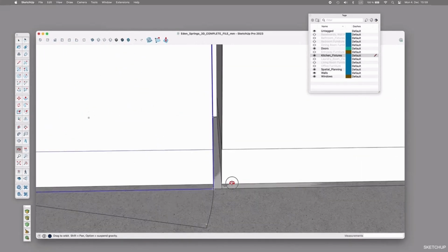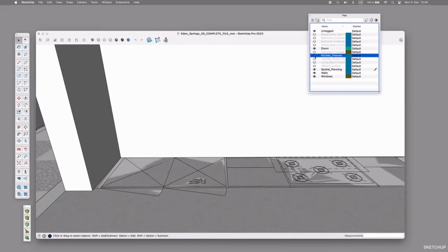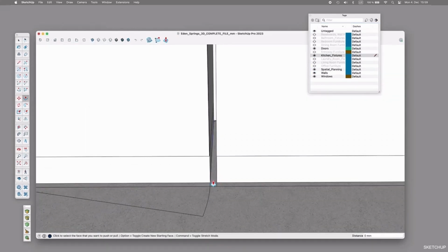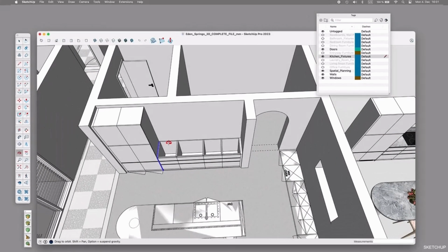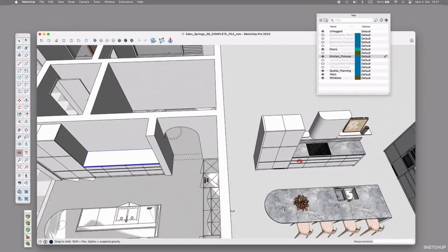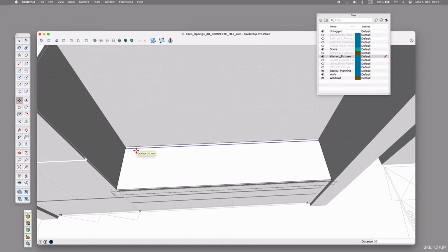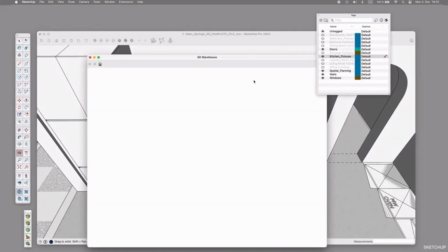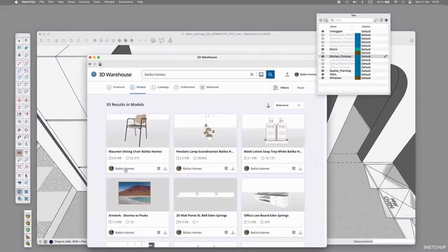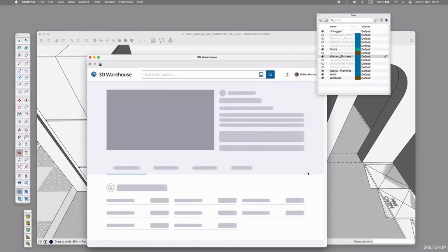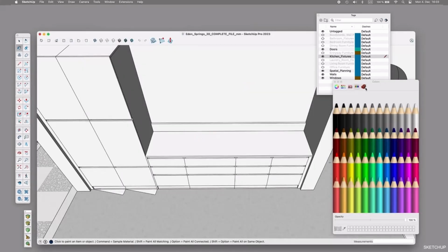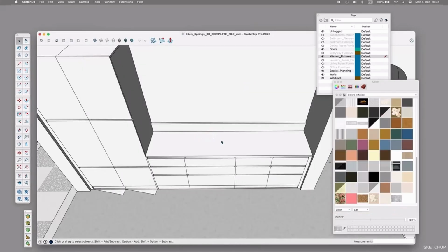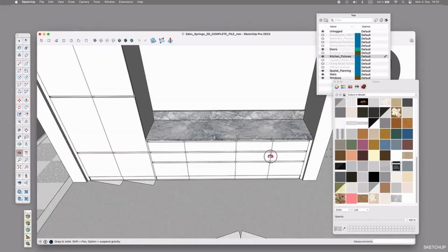If you're venturing into the realm of kitchen design, it's crucial to grasp the concept of integrating filler pieces, much like the example I'm showing here with my bottom cabinet and high cabinet. Filler pieces play a dual role. Sometimes they are a deliberate design choice, adding a touch of finesse, while other times they serve the practical purpose of filling gaps. Imagine you have aligned multiple cabinetry boxes and suddenly end up with a 3 or 4 centimeter gap. That's where filler pieces come into play, seamlessly merging functionality with aesthetics.